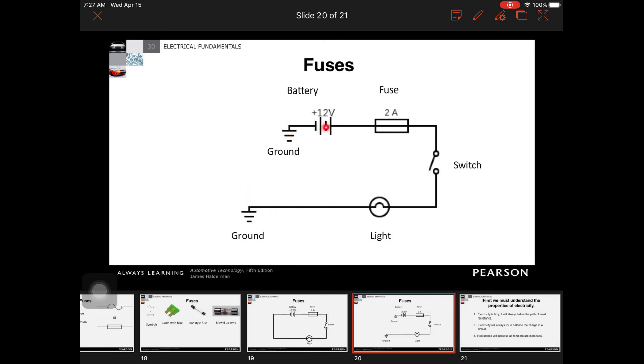So in this situation, let's say this is the interior lamp on the vehicle. We hit the little switch on our dash to turn the interior lamps on, and then this happens to ground through the body right underneath the dash. And then the battery happens to hook up to the body right next to the battery, let's say. So the ground path is actually going through the body to get back to the battery, okay? So when you see a symbol like this, that's what it means when we just put a ground down, okay?